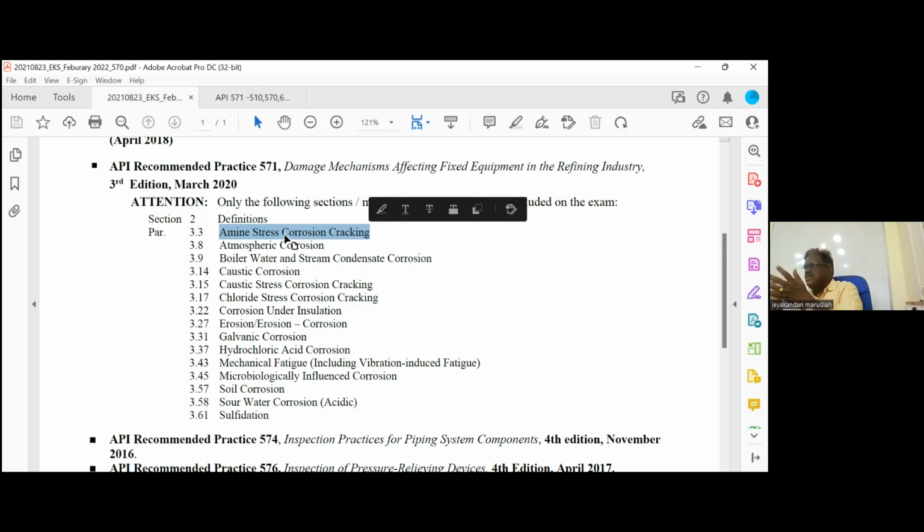So I think you know that a crack may be missed by radiography. Crack, lack of fusion, lack of penetration. This type of linear defect or planar defect can be missed by radiography. So radiography is not a preferred NDT for planar defects. It is best for volumetric defects: porosity, slag, undercut.